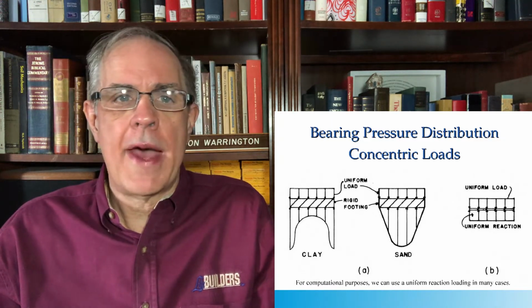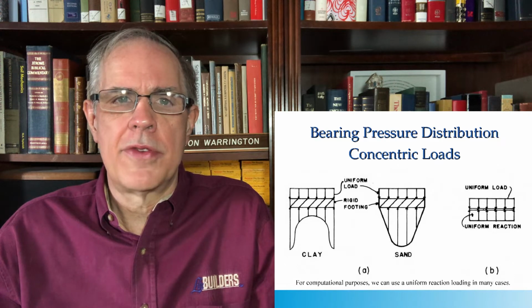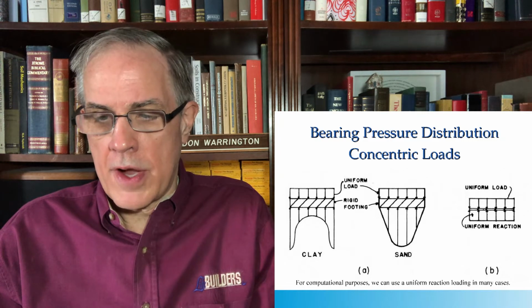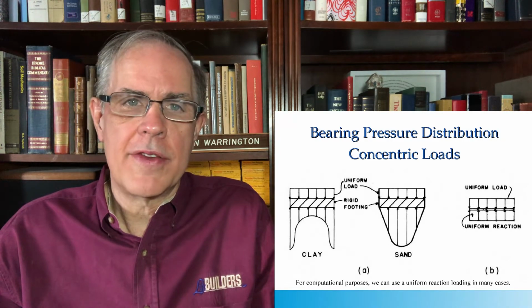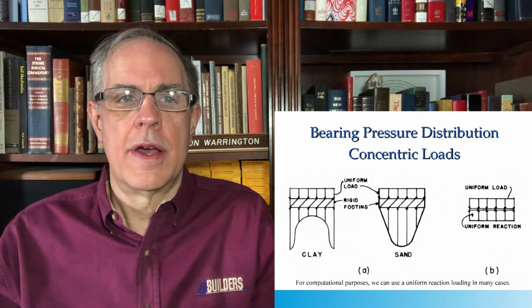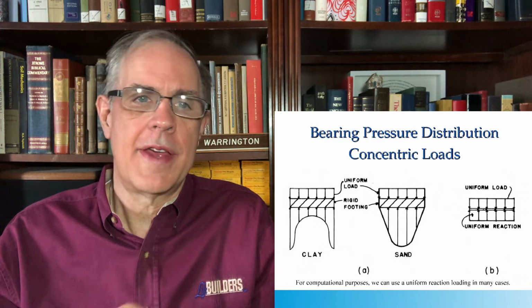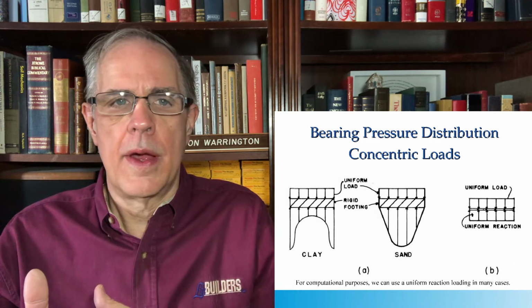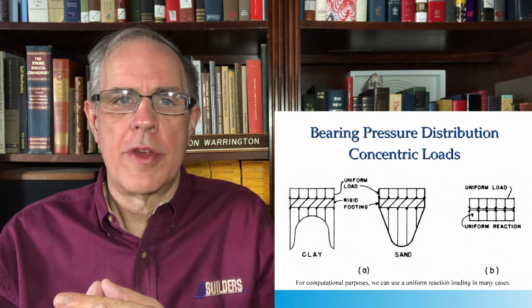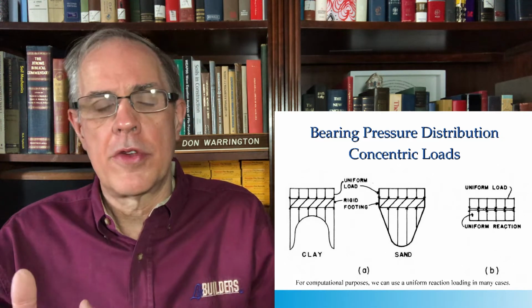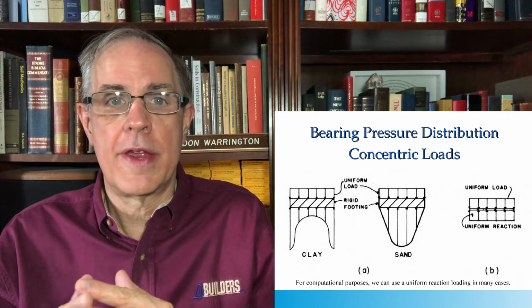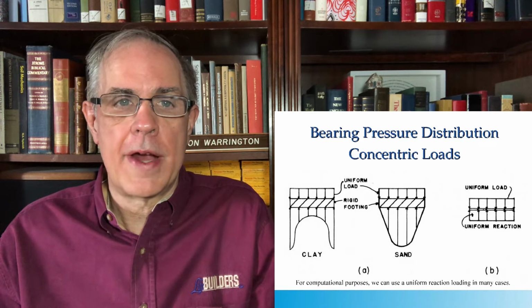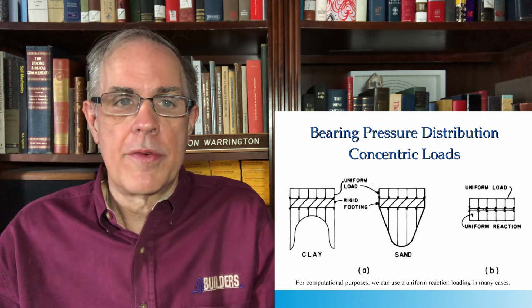One thing we're going to come back to, and we discussed some of this in soil mechanics, is the issue of bearing pressure distribution. We talked about the fact that rigid footings and flexible footings have a different distribution. We talked in soil mechanics about what the theory of elasticity tells us, but here we're going to look at a more practical view. This is a simpler and more practical view of a rigid footing on a clay soil.